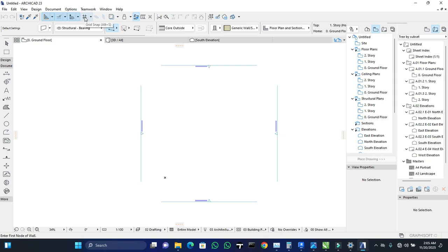The next one is grid snap. Okay, I already talked about it. Horizontal Shift+E, vertical, I think it's the same thing, Shift+E. So this is the trace tool, Alt+F2. The trace tool works this way. If you want to see what is on another floor while you are on the current floor, you can use the trace tool. You can use it to select the particular floor you want to be seen while you are drawing the current floor, so it can guide you to know where to place certain elements. Alright, so that's it for the trace tool.